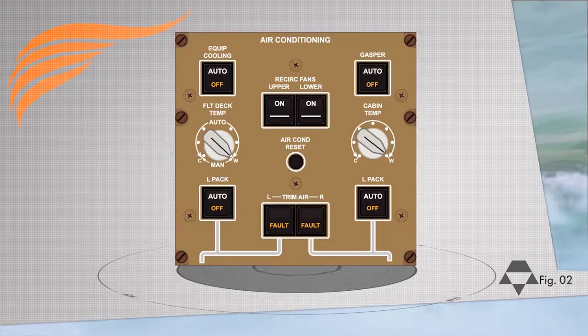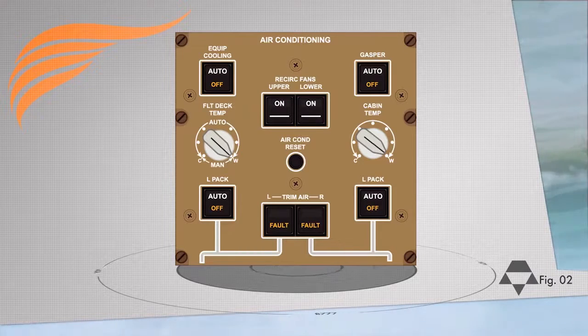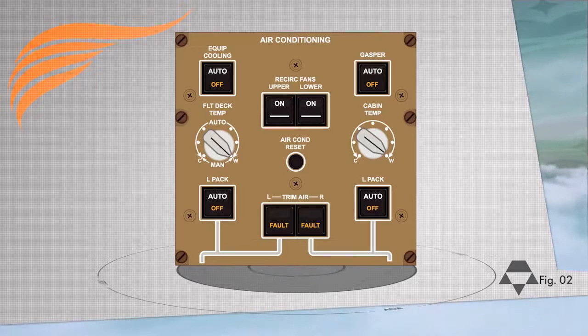For the cabin sections at least, there are auto comfort correction features that automatically compensate for temperature changes during different flight phases. For example, a cruise condition would cause the cabin temperature controllers, which we'll now refer to as CTCs, to adjust the cabin temperature up to ensure that the cabin stays at a comfortable temperature when the aircraft's skin is exposed to about -50 degrees Celsius at high altitudes.